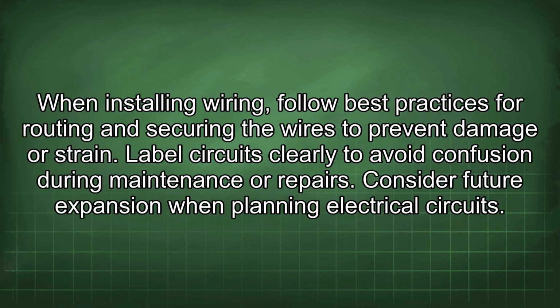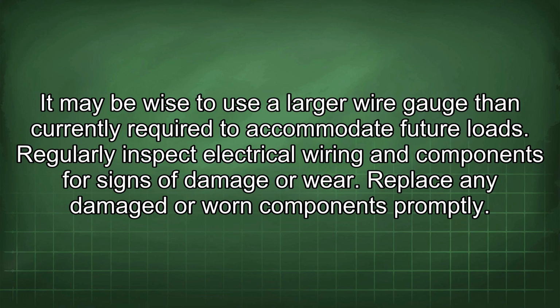When installing wiring, follow best practices for routing and securing the wires to prevent damage or strain. Label circuits clearly to avoid confusion during maintenance or repairs. Consider future expansion when planning electrical circuits. It may be wise to use a larger wire gauge than currently required to accommodate future loads.